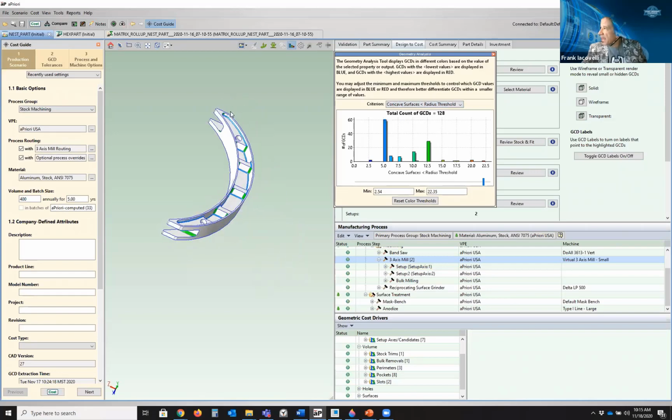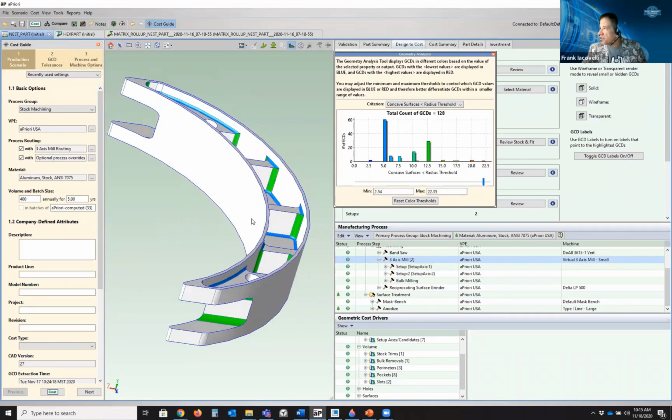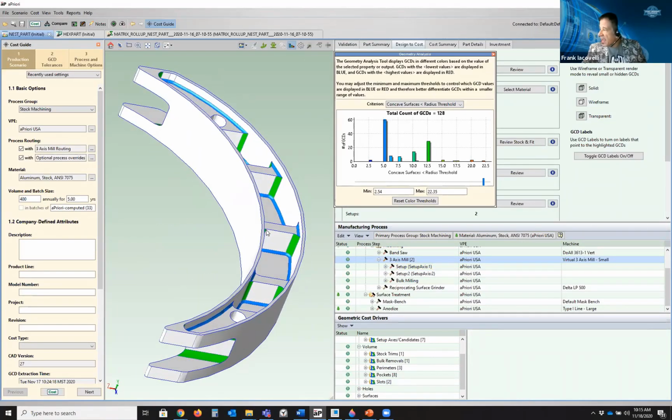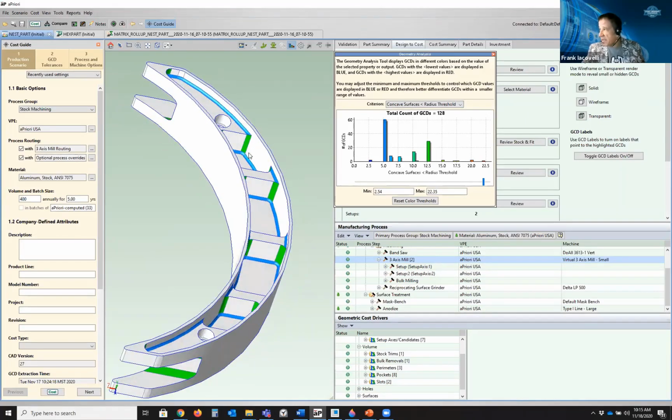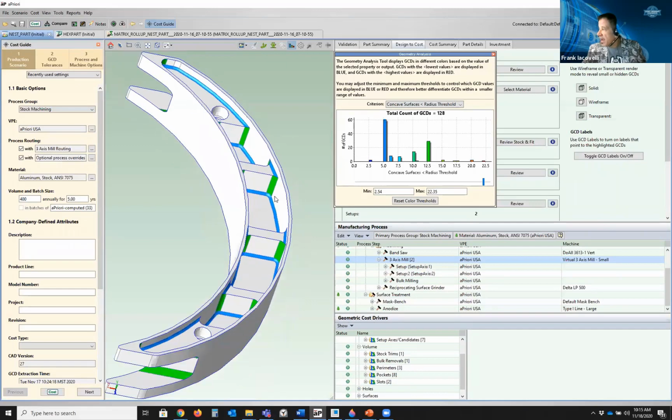And this one, you have to kind of understand how this works, but what it does is highlights with colors what your geometry looks like. And you can assess rounding strategies. So in this case here, this is what I like to see. The best rounding is where you've got your walls one color, your floors another color, and they're very consistent. You only have two different colors. So you can machine everything with one end mill. Sometimes you can't always do that, but this is optimized.